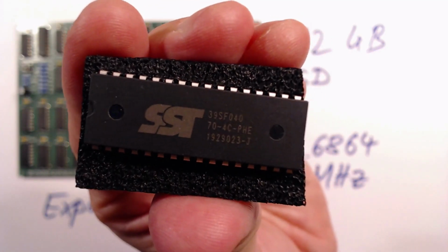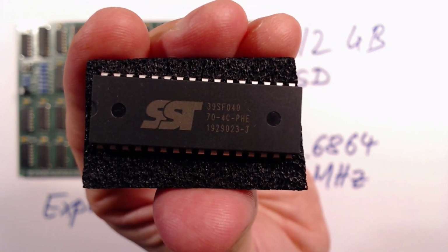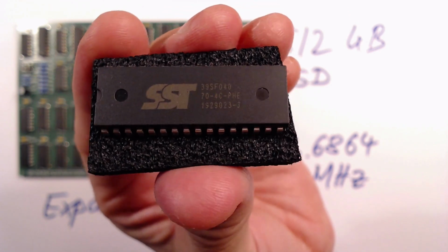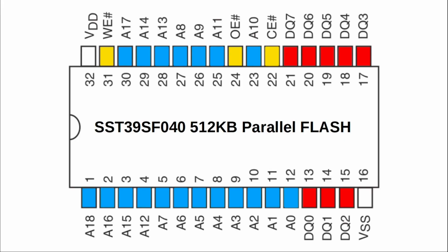I'm using these flash ICs here that cost only a little more than $1 and provide 512 kilobytes on a 19-bit wide parallel address bus. But since our CPU so far can only make use of 32K, the upper four address lines, A15 to A18, need to be tied to ground, rendering 480 of the 512 kilobytes useless. That's got to be changed.